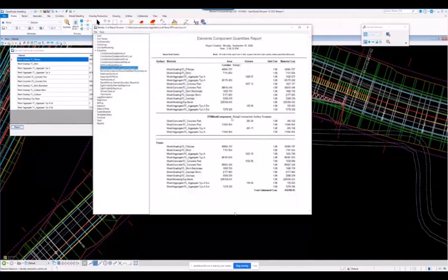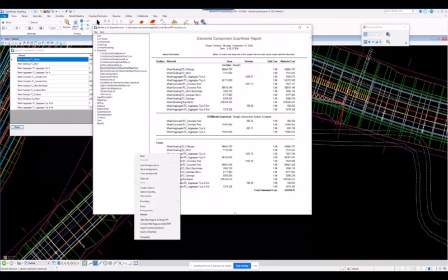Nice part is I could open up an XML report, and I could get it in a report where I could see it, and it also breaks it up for, hey, this is a surface template, this is the corridor, and I could punch that out and get it in Excel and start generating those costs. Maybe separate it. Hey, this is ramp C. I want just this information instead of looking at the whole colossal of design here, because it's just too massive for me to digest, especially for what my purpose is on this job.